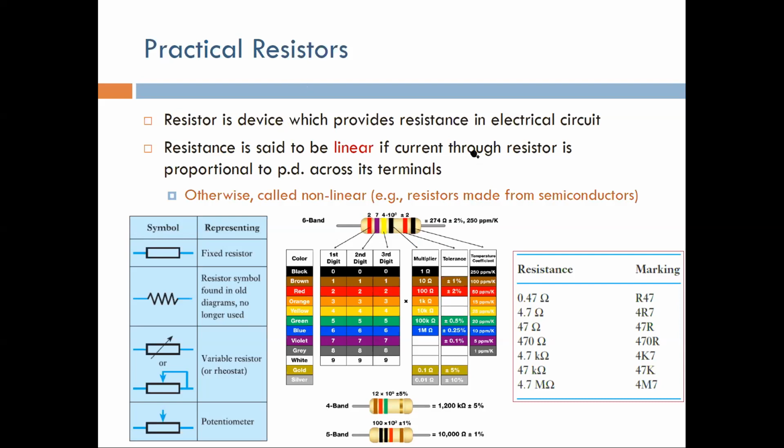Doctor, in the surface-mounted resistor, if it has 4 digits, do we still count it like 3? Basically it's computed for 4 digits. The surface-mounted ones do not have tolerance digits. So assume that you have 4 digits like this: you have 3 numbers times 10 to the 4th. It's different because you don't have any way of having the tolerance in the code.